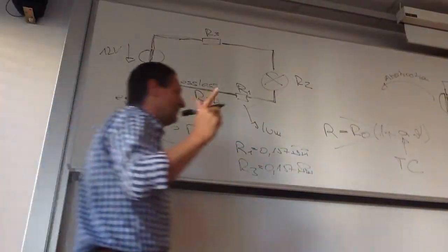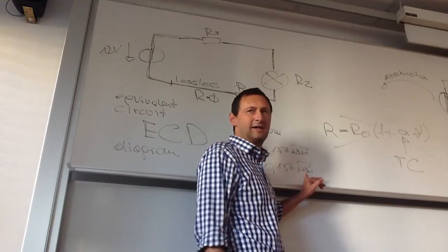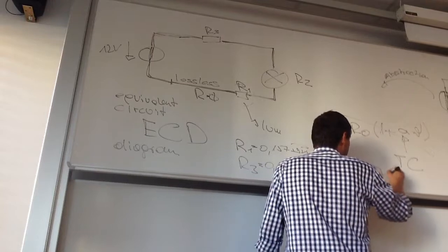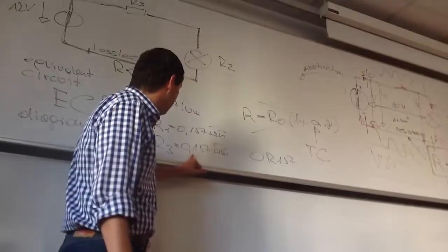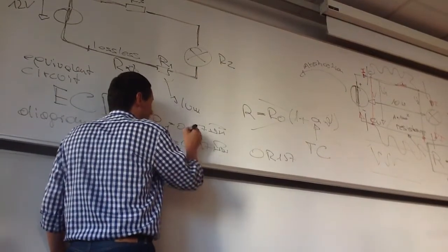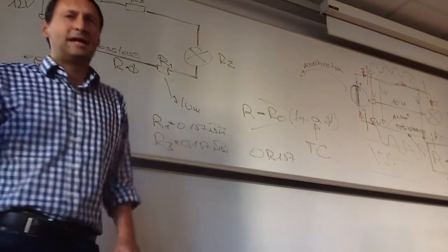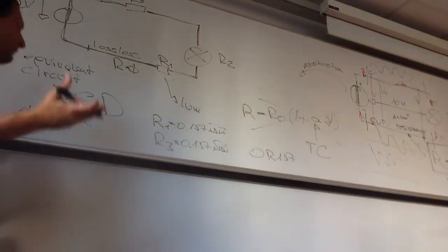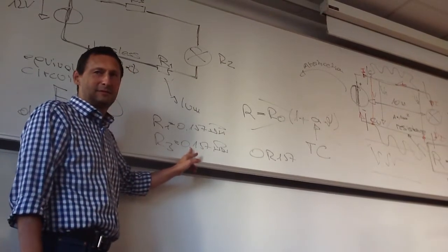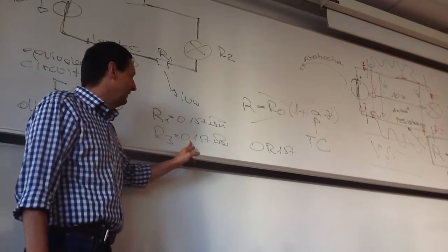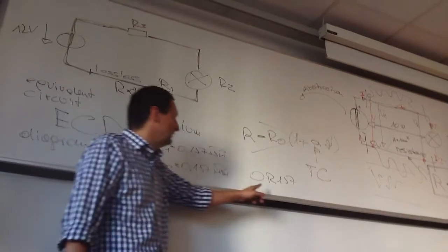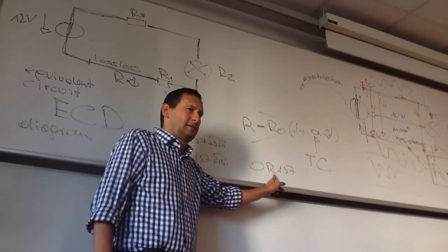That's why you will never see an ohm character in a circuit diagram. Normally you write 0R175. You also omit the decimal point, because in English it's just a point. If you copy the circuit diagram maybe 100 times, then you will not see this decimal point in the diagram. Therefore, for the decimal points we use R.